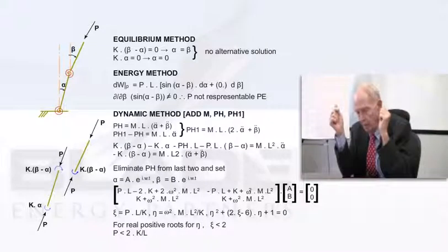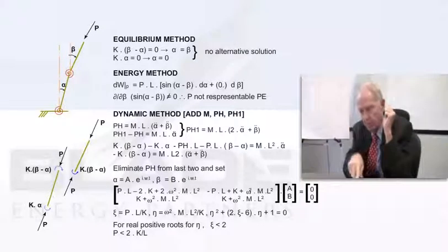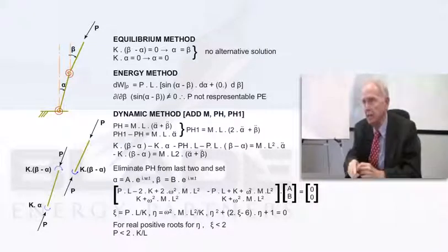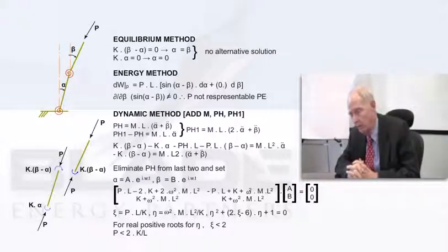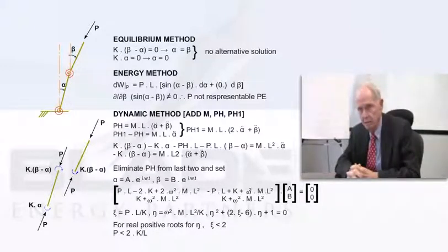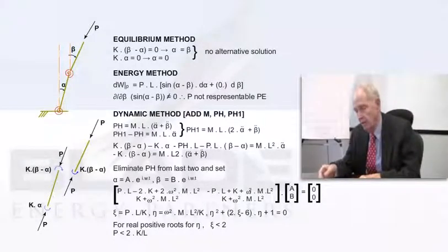So I can do that with all of these problems, and in every case I can say that a small lateral load can be used to test stability. And in those cases, it's only going to come back if the spring constant is positive. That means that the load goes up when I push on it. Okay? That's the key.